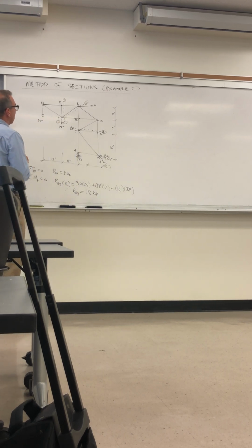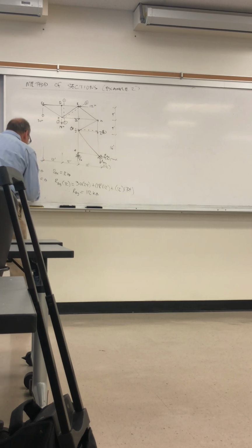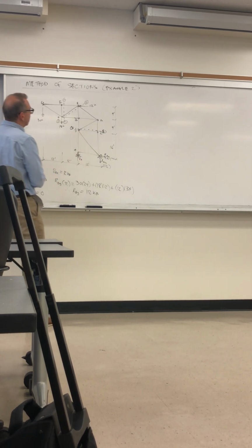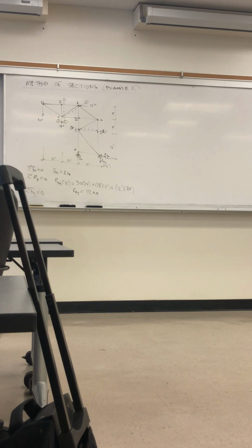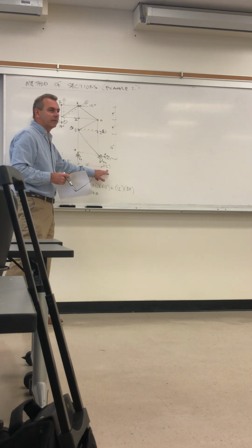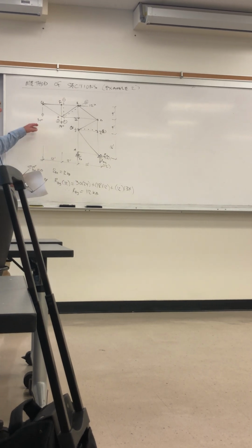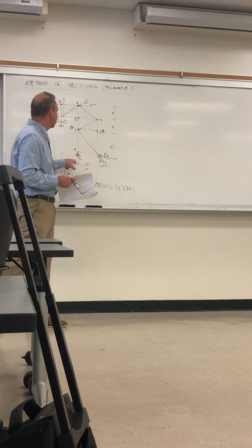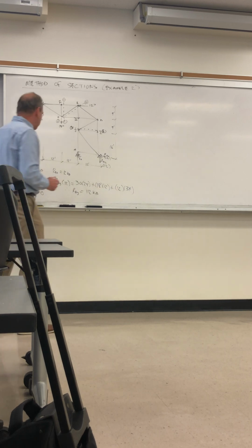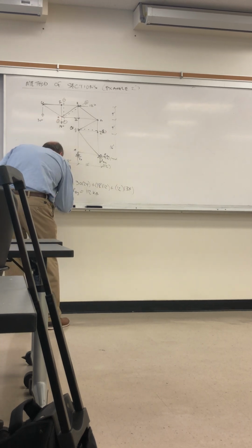Okay, so summation of forces in the vertical direction is 0. I'm doing that just to solve for R sub A. That's the only unknown reaction. 3 reactions, 3 equations. And you can see R sub A is up, everything else is down, including this reaction, for the reasons that I gave. So I have 30 plus 18 plus 112 has to be, there's nothing else in the vertical direction. So I have R sub A, which only has a vertical component.